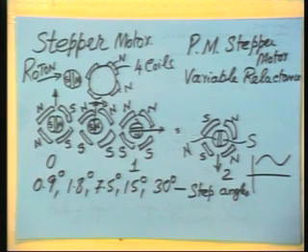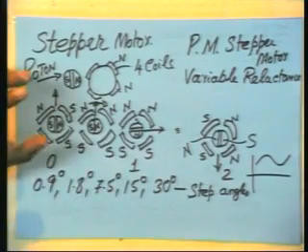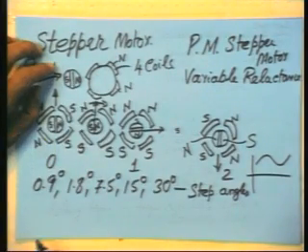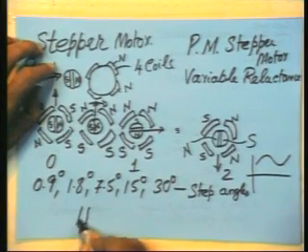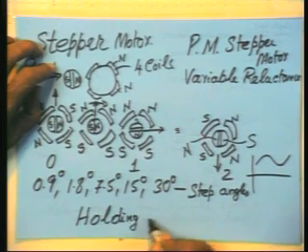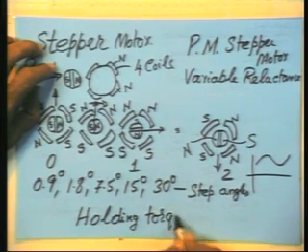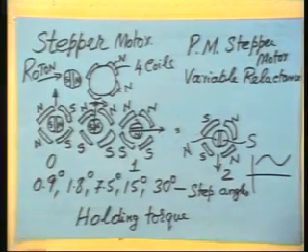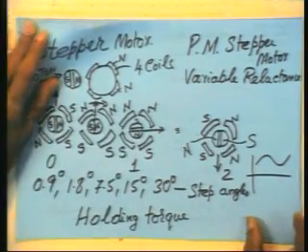If the friction. There is one more thing with the stepper motor which you should know, what is known as the holding torque. If you energize the stepper motor, the shaft does not rotate, but it can hold on to a particular load. One could show it like this.